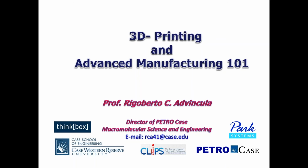But the advantage is when you're trying to do prototyping, when you want to get the object, you actually do it faster, because sometimes prototyping involves submitting a sample to a manufacturing lab or a tooling shop where they have to apply subtractive CNC milling in order to produce the part. So in that case, 3D printing has an advantage in speed in terms of prototypes. But at any rate, 3D printing cannot compete with high throughput manufacturing methods such as injection molding and blow molding, which can produce parts relatively inexpensively, especially at high volume and in a fast manner.